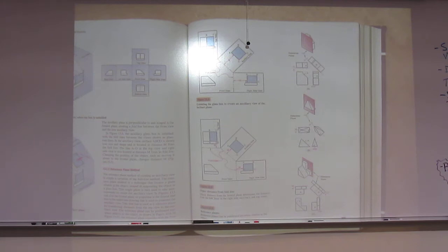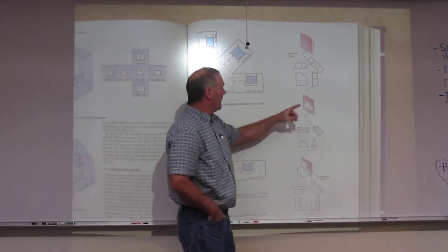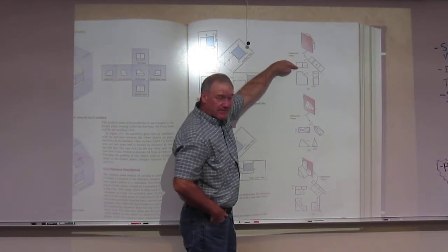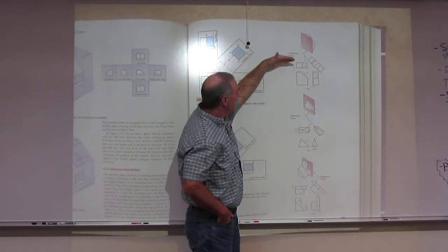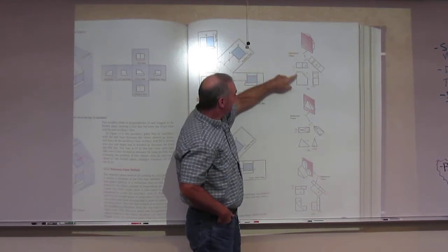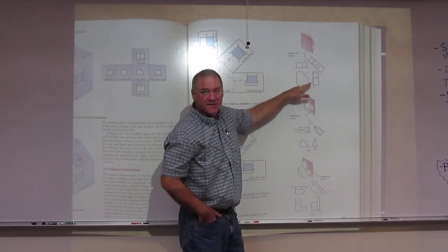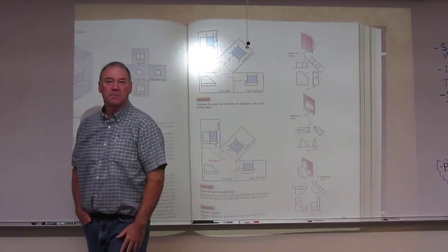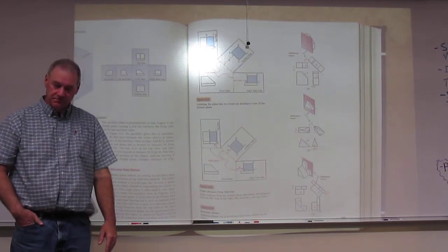Can I ask you, so when you're doing your reference plane, you measure from your view up the same distance from each side? No. The only thing we're worried about on the reference plane is the distance from the reference plane on one of these views to any feature on here. That's all we need. The distance in between the front and the top, and the front and the right, is irrelevant. It doesn't matter a bit. We can have them wherever we want. You only get depth, not the other uses. That is correct. Okay.